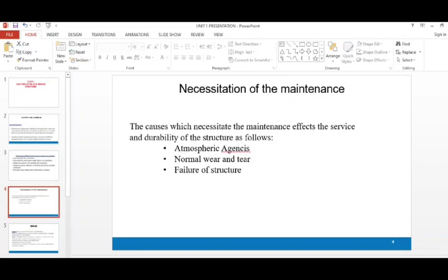And then we can also say the expansion and contractions. The material is subjected to repetitive expansions and contractions while they become wet and dry, and they develop stresses. The expansion of water and the variation of temperature cause expansion and contraction, absorb water and affect the microstructures of a material. And chemical: the water available in nature usually contains acids, alkalines and other compounds in dissolved form, which act over the material and cause chemical weathering.